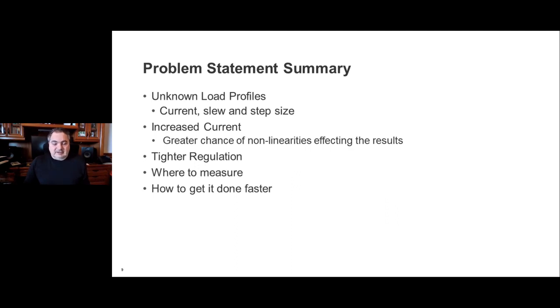There's diode emulation, and there's power saving techniques that every architecture implements. And of course, every vendor has slightly different ways of implementing these architectures. So there's different things we need to be looking out for, and we don't know quite how exactly they're going to react. The increased current offers a lot of potential for some peculiar corner case activity that we're not going to be aware of until you actually get that product and you're actually slamming the rails itself.